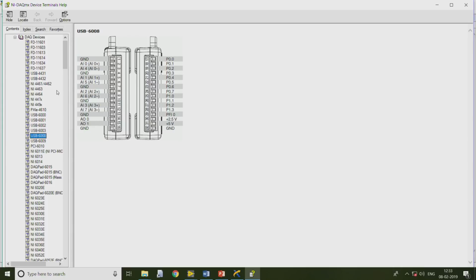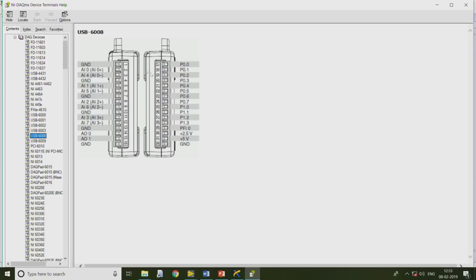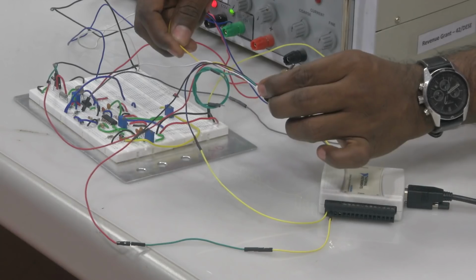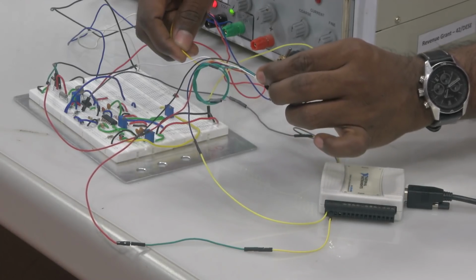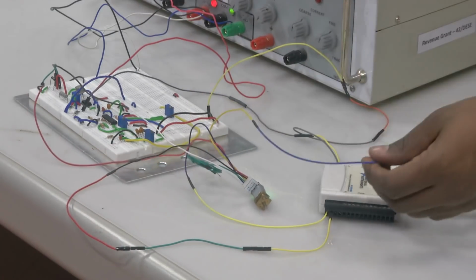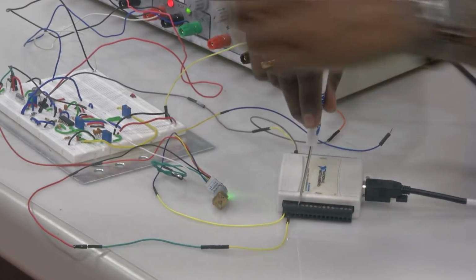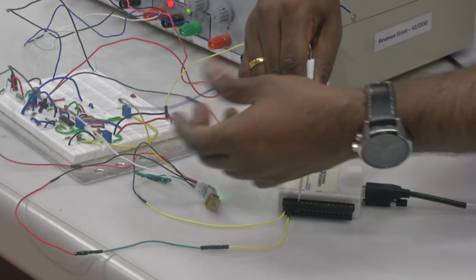So, if I look into the data sheet of the NI 6008, here if you observe, we can see that PFI, the 29th terminal, is our counter pin. So, let me connect the output of the clock pulses. In this case I am considering C1; either you can go with C1 or C2, I am taking C1. So, I am giving it to a counter input.